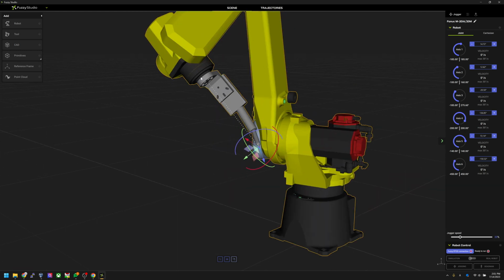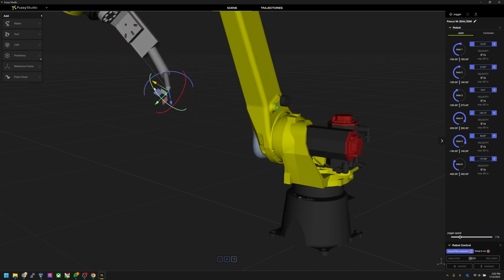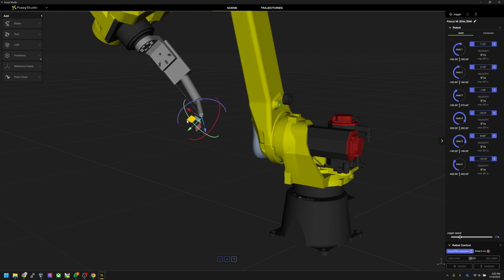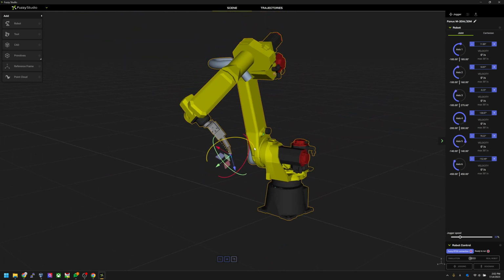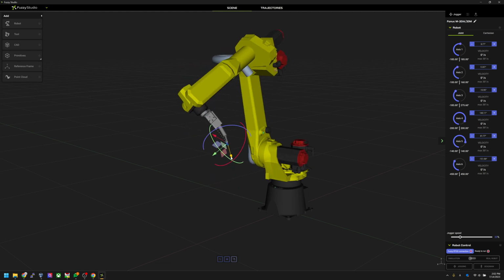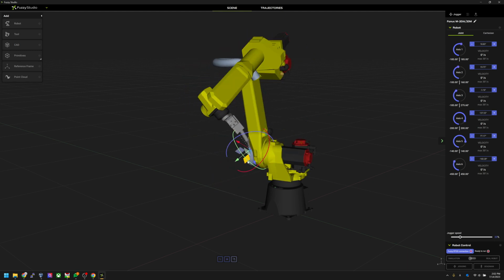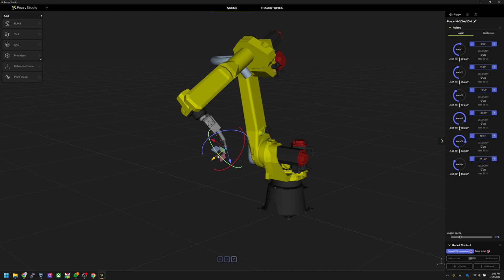So in here, you see a small line. It means this is from your robot's flange to the TCP point. And then you can just operate your TCP, your tool, like what I explained before. Great, all the same, you don't need any special button, no need for any special setting. It's the same operation for any tool.